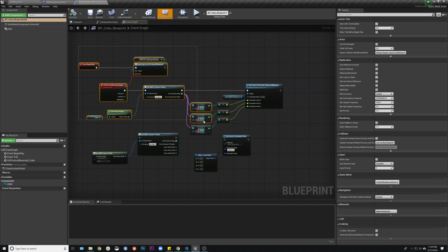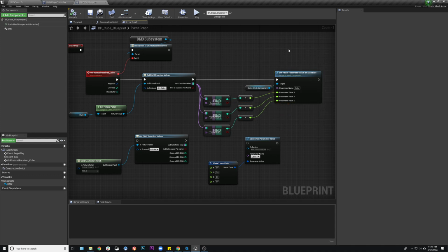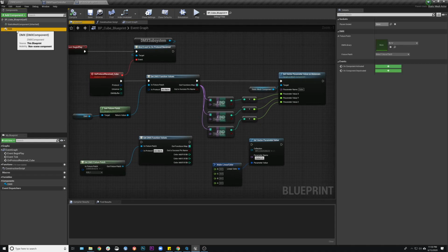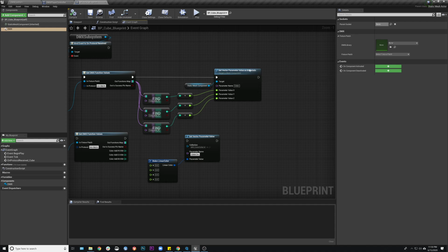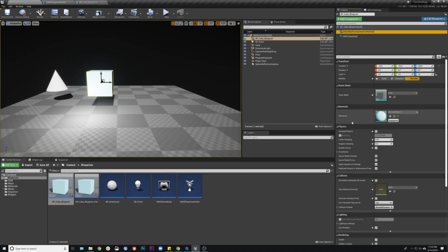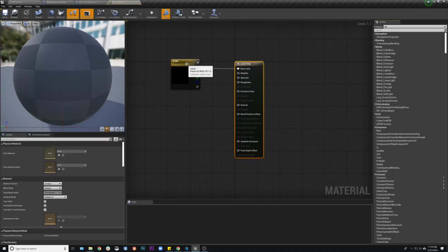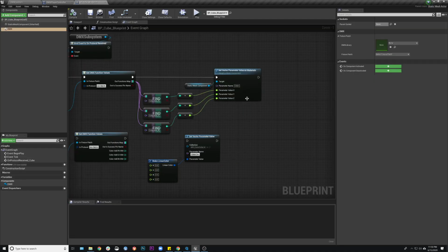Again, I'm doing pretty much the exact same thing. However, there is a very important difference about how I'm actually trying to set the value on this. The beginning part is all the same. We're going to get the patch from this DMX component, and we're going to do the color, the fine to get the RGB. But there is no set light color because it's a mesh and it just has a material attached to it. So if I look at the actual mesh component, it's got this material instance color only on it. What that actually is, I've created a material called color only, and it has a material instance attached to it. So I've taken just a color node that's a parameter, put it in the base color, and that is it. It's color only. That's kind of why I called it that.